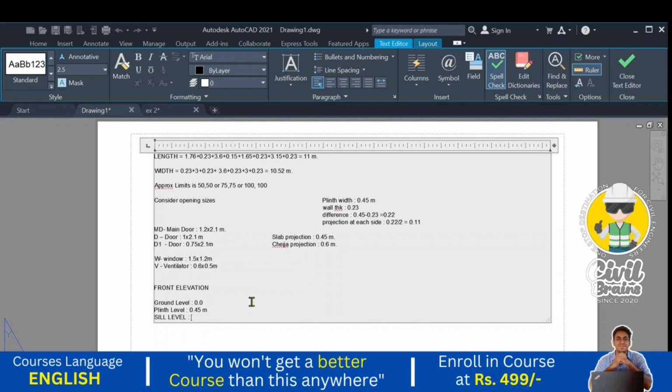But in this particular drawing, all the windows are 1.5 meter by 1.2 meters. So 1.5 meter is the width of the window, and 1.2 meter is the height of the window. So what is the sill level? We need to calculate that. How to calculate the sill level? So total height is how much? 2.1 meter.